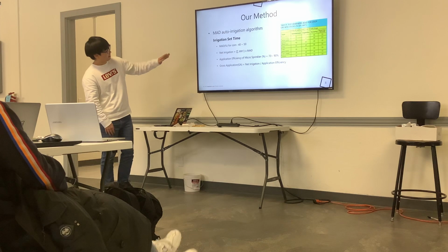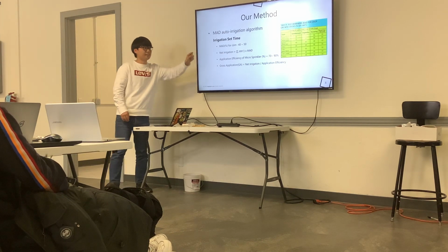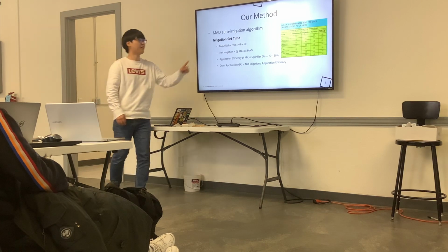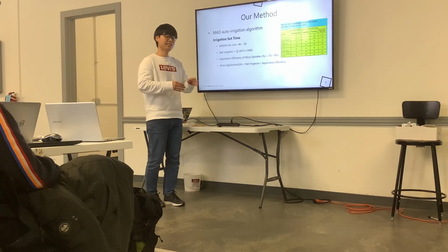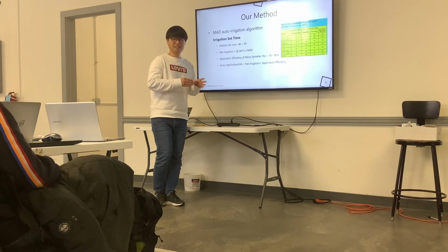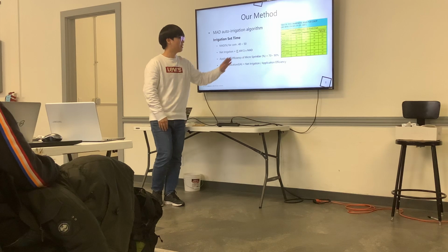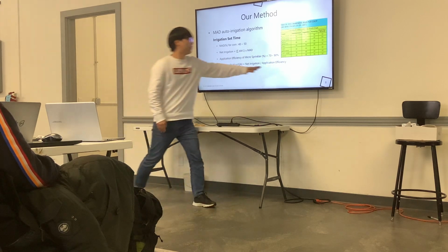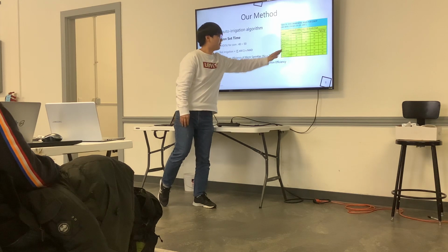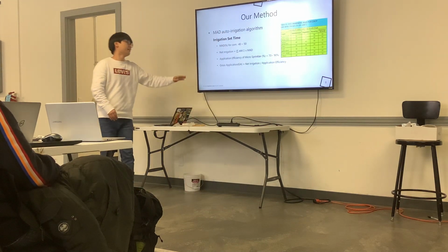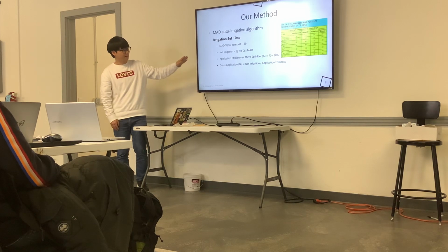Let's calculate. First, we can find the MAD point in this table. This table shows the recommended MAD point for each crop at each stage of its life. Corn is 40% to 50%. Total AWC times MAD gives the net application.